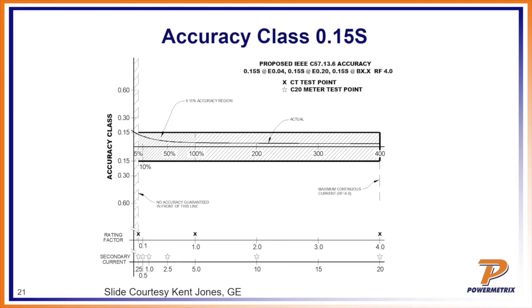So this is under lab conditions, and it's assumed at 30 degrees C, which is around 86 degrees Fahrenheit. That was where it holds its accuracy. So as burden increases and as temperature increases, which is a very common phenomenon we have in the field, this accuracy is not guaranteed anymore, or it derates.